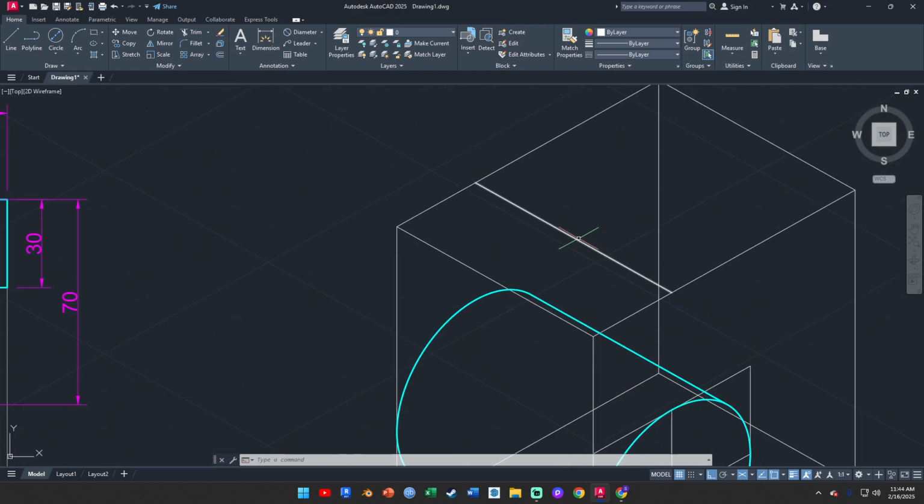And we know that the length is supposed to be 40, so we could probably shorten it, right? So as of now it's at 75, so when you minus 75 from 40, it means that we gotta reduce it by 35. So you move it up and you type in 35, and if I measure it, yeah, you see it's 40.